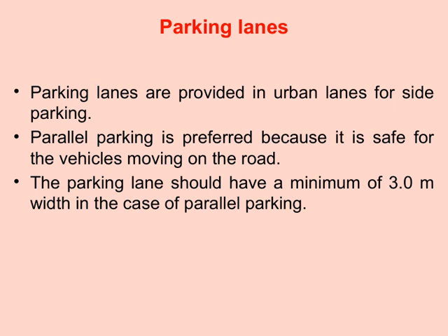Now, among the different types of parking, parallel parking is generally preferred. Why? Because it's safer for vehicles that are already on the move, reducing the chances of accidents or disruptions. When designing these parking lanes, it's important to ensure they have a minimum width of about 3 meters for parallel parking. This width provides enough space for vehicles to park comfortably and safely, while also allowing room for opening doors and pedestrian movement. Overall, properly designed parking lanes help maintain smooth traffic flow and enhance safety for everyone on the road.